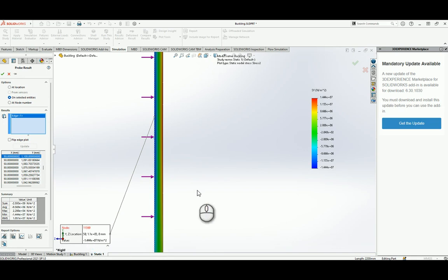Now, in your MATLAB script, if you were to make P equal to 0, if we just revisit the equations for the stress and for the displacement, you'll notice that we have P in the denominators. And if P is 0, therefore we will have infinity, or MATLAB will give an error, not a number. So what you need to do is, instead of making P equal to 0, make it 0.1 or 1 Newton. Make it a very small value so that numerically you would not get that infinity issue.